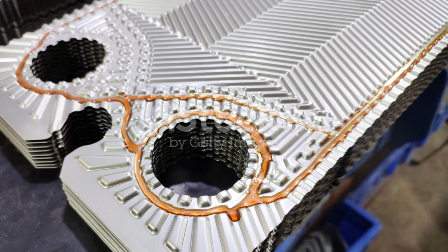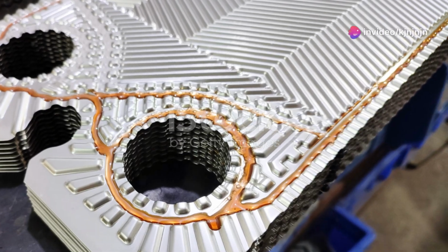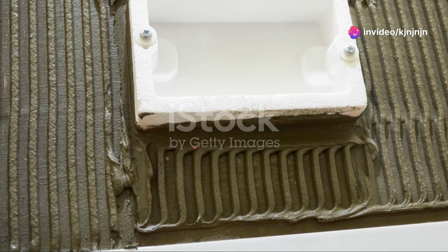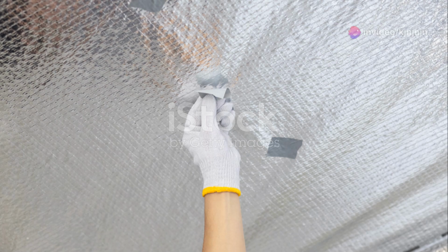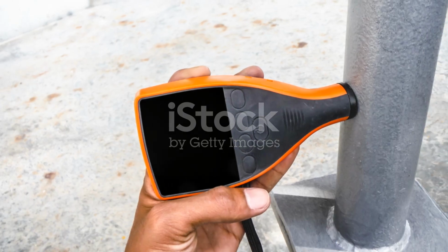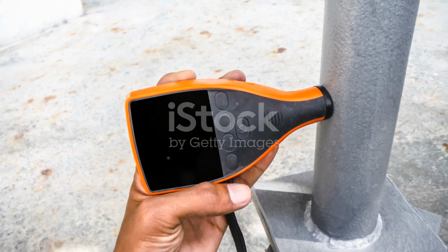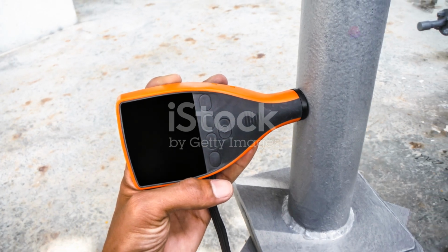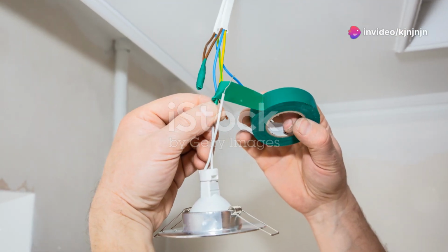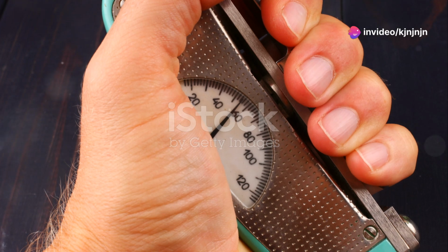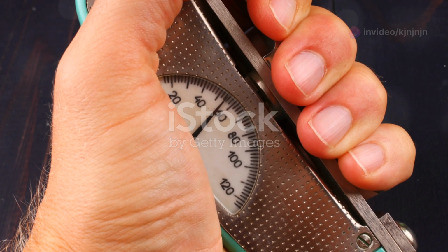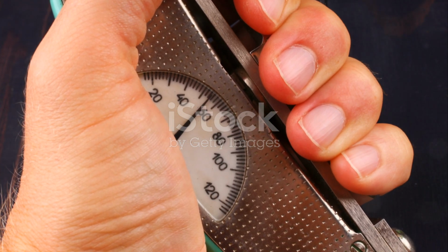Adhesives play a critical role in the performance of strain gauges. The adhesive bonds the gauge to the material, ensuring that it accurately reflects the material's deformation. The adhesive must be strong enough to withstand the applied loads and environmental conditions. It should also have good electrical insulation properties to prevent current leakage. Choosing the right adhesive is crucial for obtaining accurate and reliable strain measurements.